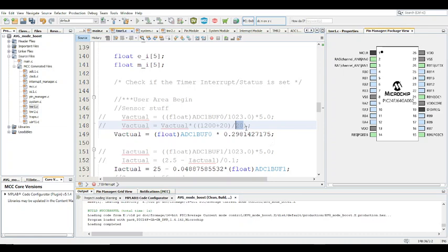So it's good to make your sensor resistors, used to sense your voltage, as high as possible. So that's that. This is how you calculate it eventually, essentially. So 5.0 is the VREF for this particular example, and the ADC is 1023. This is essentially 2 to the power of 10 minus 1. So it's a 10-bit ADC, that's why this value is there.